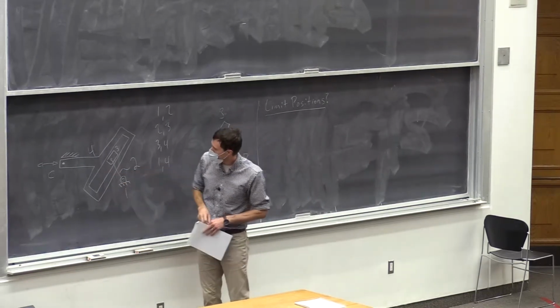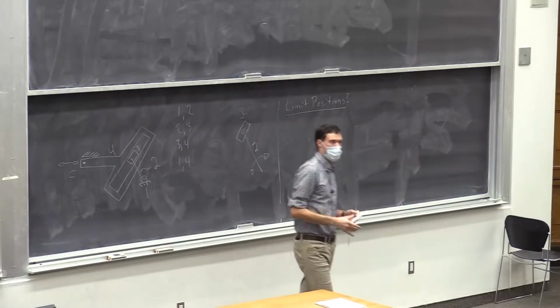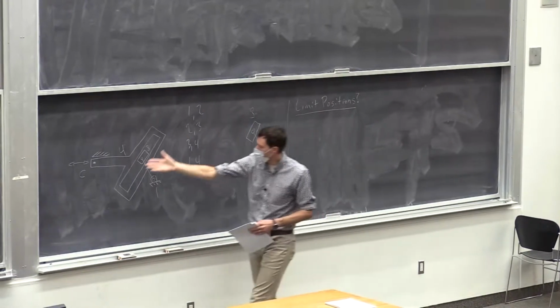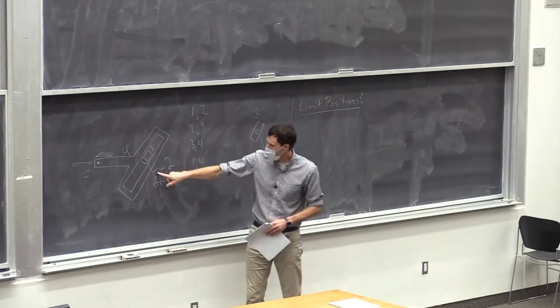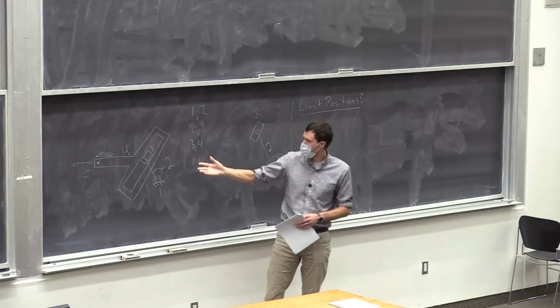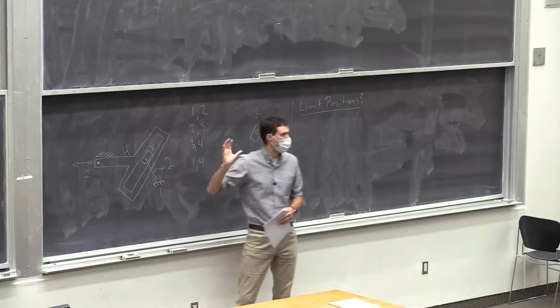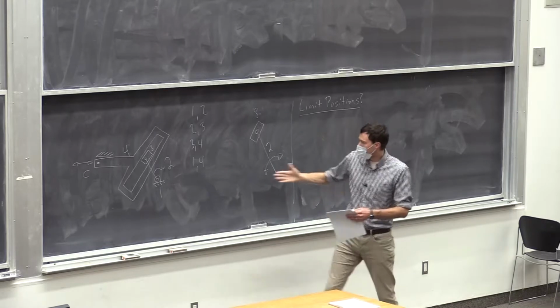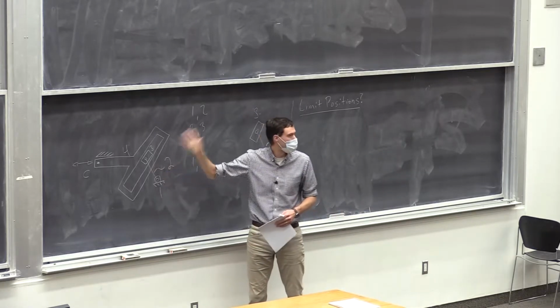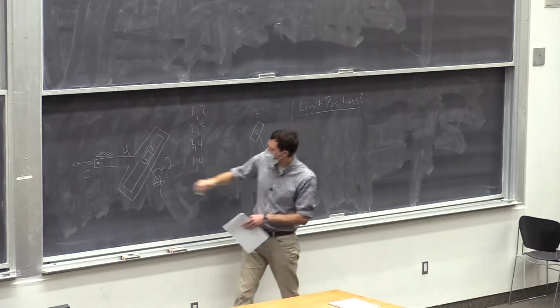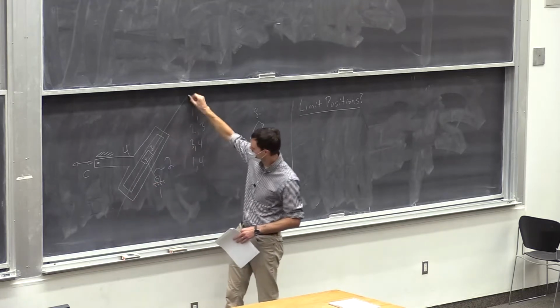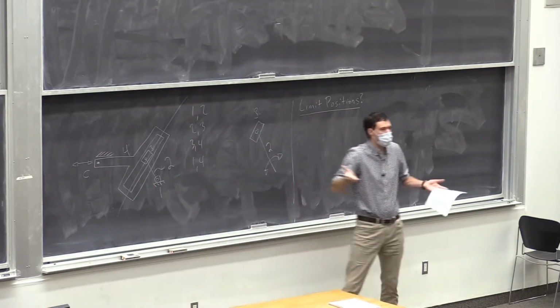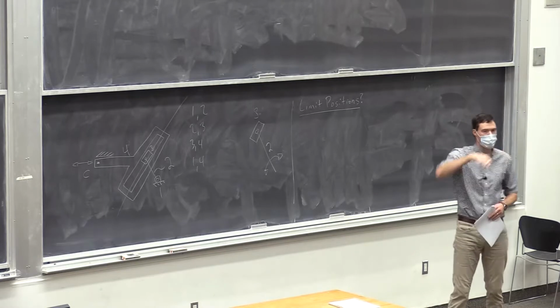So for this mechanism, I would suggest this is a nice one because the geometry is pretty simple. You have link 2 going round and round, and link 4 going back and forth. That's really all that's happening here. So link 2 is the only thing that has an angle changing. So where we have this long axis, that's really the only axis of interest. And then there's like up, down, left, right.